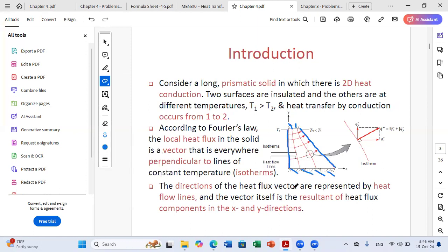Because you don't have the same area and not the same shape, if you follow the heat flux line, the heat flux will have two dimensions here, and it will be perpendicular to the lines of constant temperature. The lines of constant temperature here will be curves, which will justify having temperature variation in two dimensions. And of course, this is much more complex than a wall of constant area. So that's why the solution of temperature distribution in this domain is more complex and can be done using an analytical method or a numerical method.